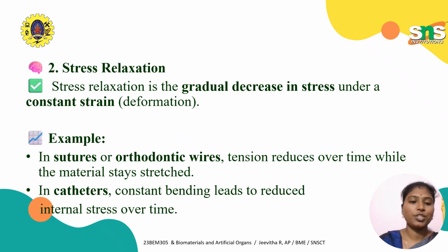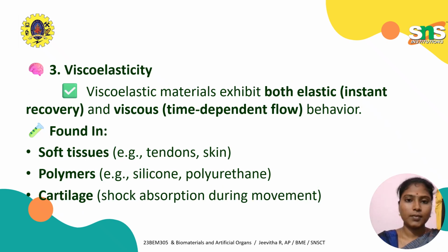And stress relaxation. Stress relaxation is the gradual decrease in stress under a constant strain. For example, in sutures or orthodontic wires, tension reduces over time while the material stays stretched. Viscoelasticity. Viscoelastic materials exhibit both viscous and elastic behavior.